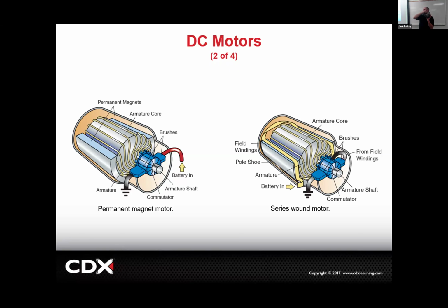Your starter's getting power, but it's not working. Your starter's no good. Now, should I measure ground? Yes, but the starter's grounded through the housing, so it doesn't really lose ground because it's bolted directly to the block. I'm like, yeah, you need a starter. And then he's like, oh, should I get a rental car? And I'm like, nah, I'll take care of it this weekend when I get a little time.